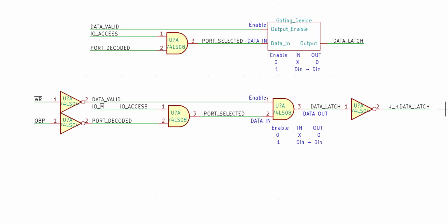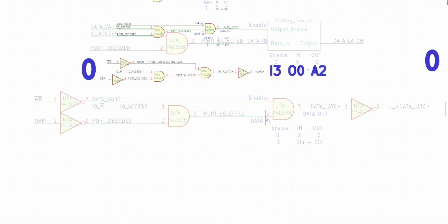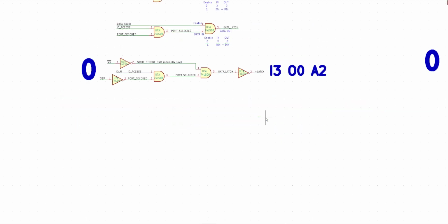And again, if we had a couple of AND gates and some inverters, we could use this circuit just the way it is. So I'm going to go ahead and put a version or circuit number on this, and do a count of the gates in that circuit so I can help package them later. I've done that. I actually made a copy of it. I restored the last version to the way it was. I've given this version number 0. Cleaned it up. We've got 3 inverters, no OR gates, and 2 AND gates.